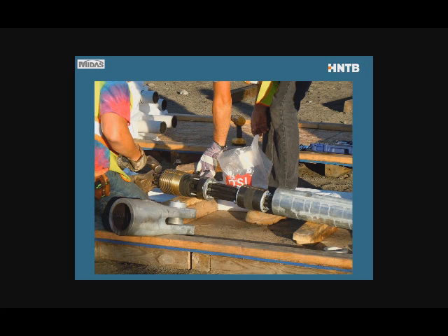Lake Champlain, by the way, was kind of a hybrid between the pinned connection with the traditional cable, with the traditional wire rope, and the strand by strand that we use for Blennerhassett. Lake Champlain also has an I-shaped arch rib, similar to what I've shown for Happy Hollow. So we didn't really have room to seat wedges and to have anchor beams in the arch rib.